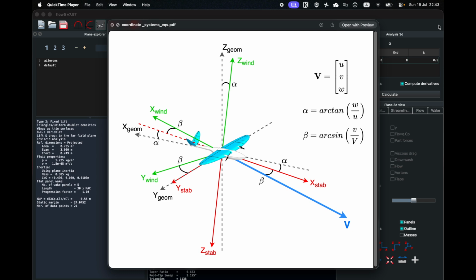If you rotate the wing by 5 degrees, the actual angle of attack of the wing will be 5 degrees greater than the analysis input. The second coordinate system is used for the output of all coefficients, forces and moments except stability derivatives.